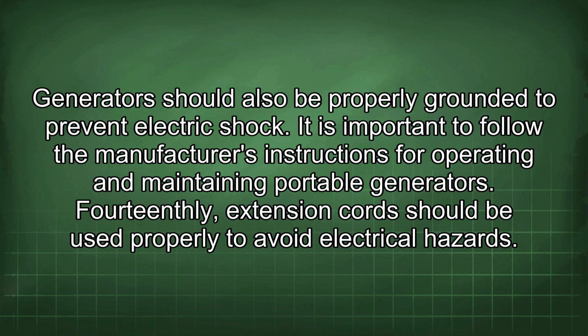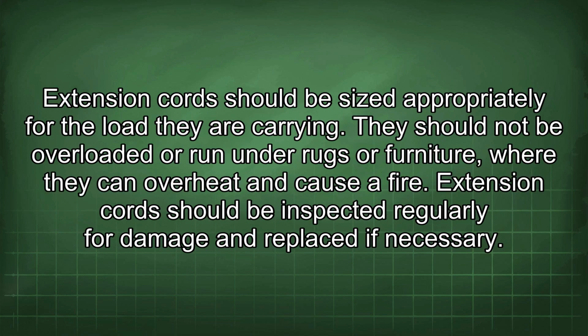Fourteenth, extension cords should be used properly to avoid electrical hazards. Extension cords should be sized appropriately for the load they are carrying. They should not be overloaded or run under rugs or furniture, where they can overheat and cause a fire. Extension cords should be inspected regularly for damage and replaced if necessary.